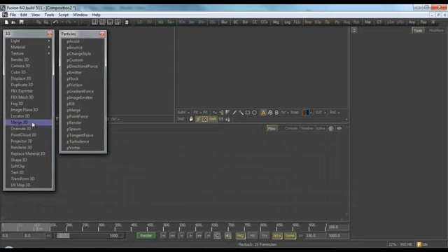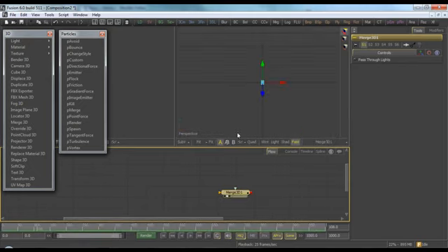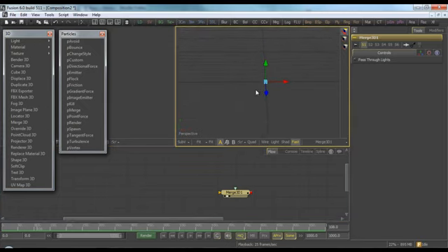First of all, we'll set up Merge 3D. What is Merge? Merge is kind of a 3D world in Fusion. Just grab it and throw it in the screen. If you press middle mouse button and left mouse button, you can zoom in, and drag left and right. If you press middle mouse button and right mouse button, you can rotate your camera, right? And with only middle mouse button, you can pan left and right.